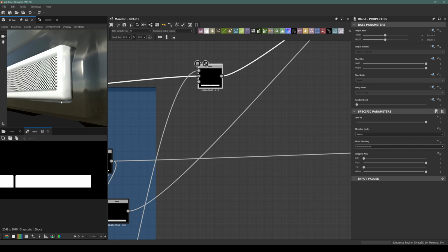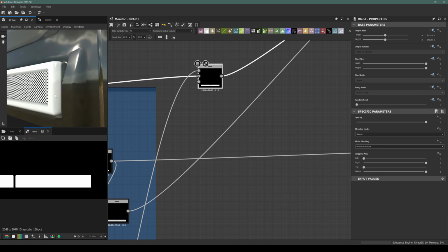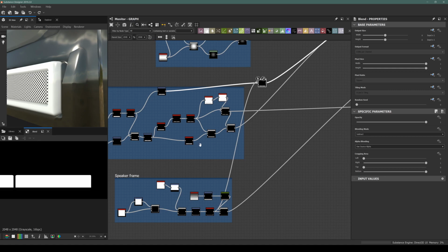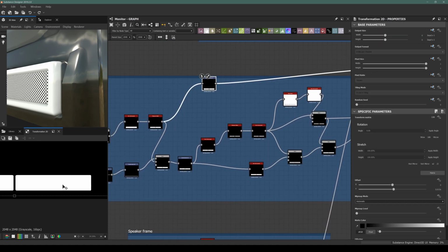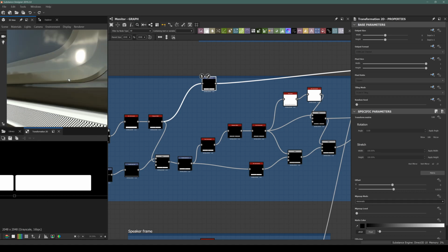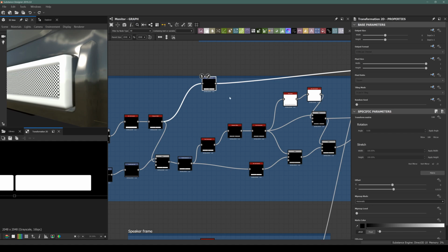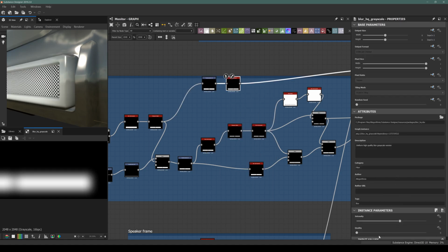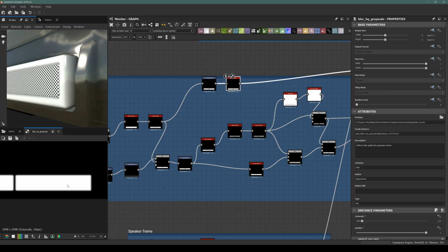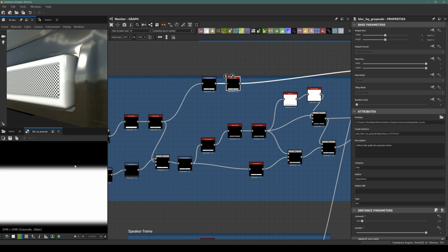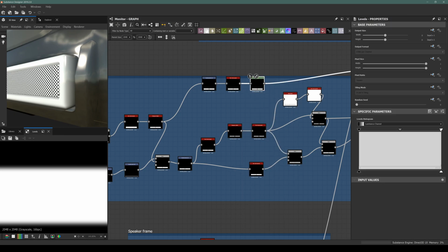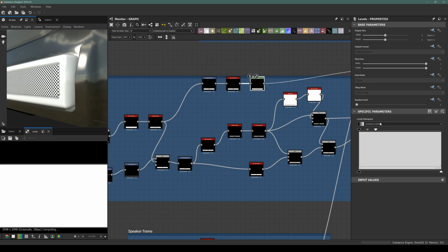My next step will be extending this mask a little bit to make the seams work better with different colors, by defining the different color with this mask. So we will extend this area to match this height map inaccuracy for this mask. To do that, I will add a Blur HQ Grayscale node and blur the shape, but you can see that blurring creates gray values outside of your mask. So we need to use a Levels node to compress the values to total white.